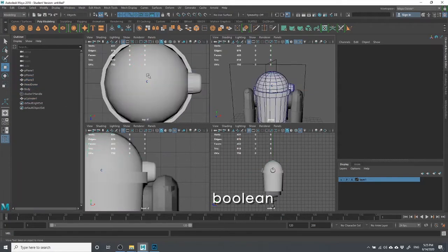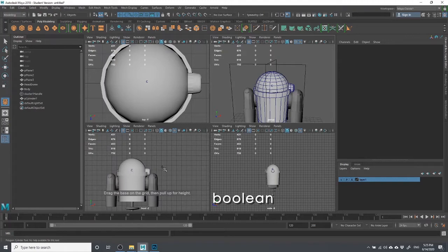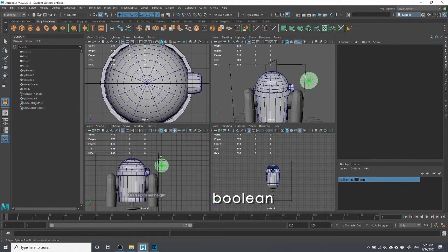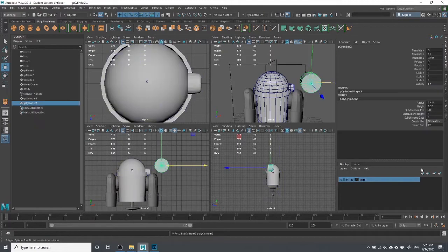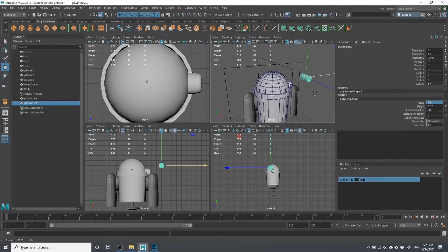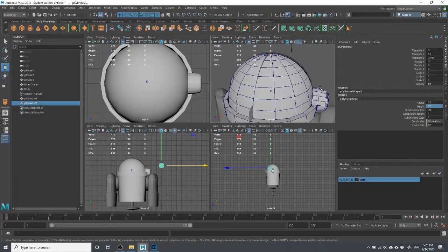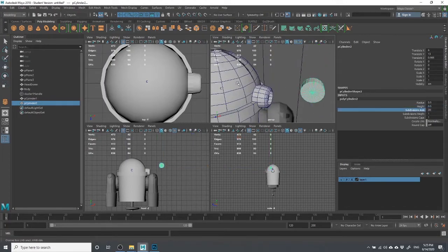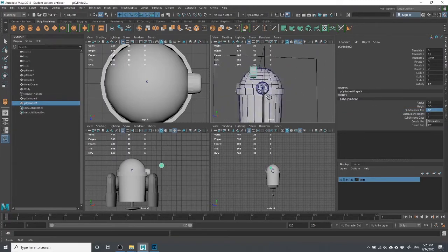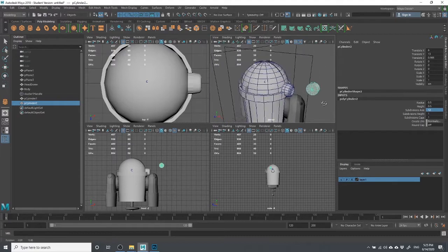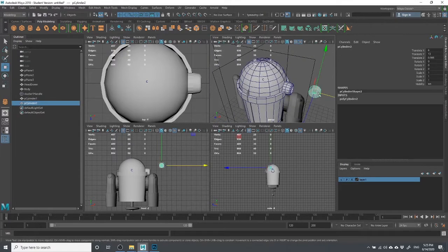What I'm going to do is define a shape here for the size of the eye, which is about this size here. Of course, it's going to be smaller, so let's have that be 0.25 or maybe 0.5. I like that, yeah, 0.5. That looks about good. Let's have that about that size here. And just because I don't feel like cleaning that much up, let's take this to say 12 or 16. Usually when I do these circles in polygonal modeling, I like to have them divisible by 4 because it's easy to deal with.